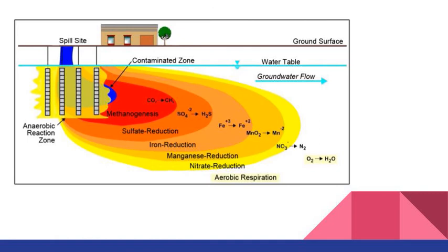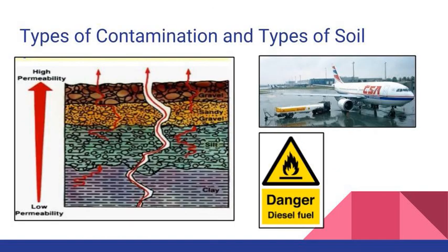The second one is the type of contamination products in the soil. Aerobic bioremediation is most often used at sites with mid-weight petroleum products, for example, diesel fuel and jet fuel, because lighter products such as gasoline tend to volatilize readily and can be removed more rapidly using other technologies like air sparging or soil vapor extraction.